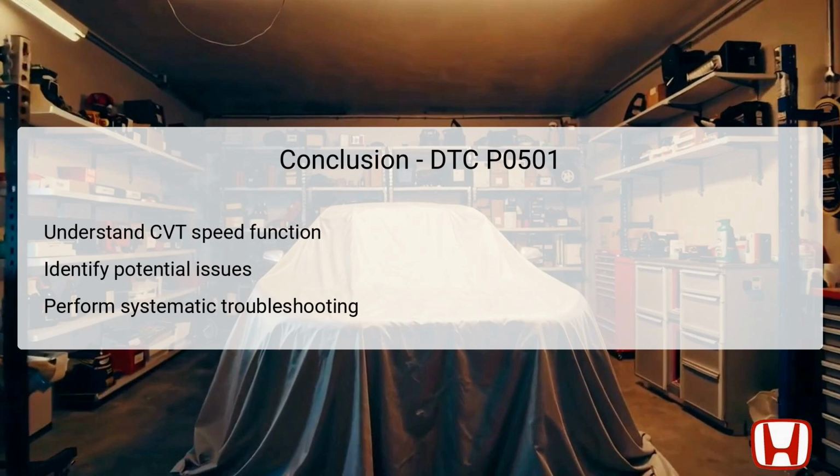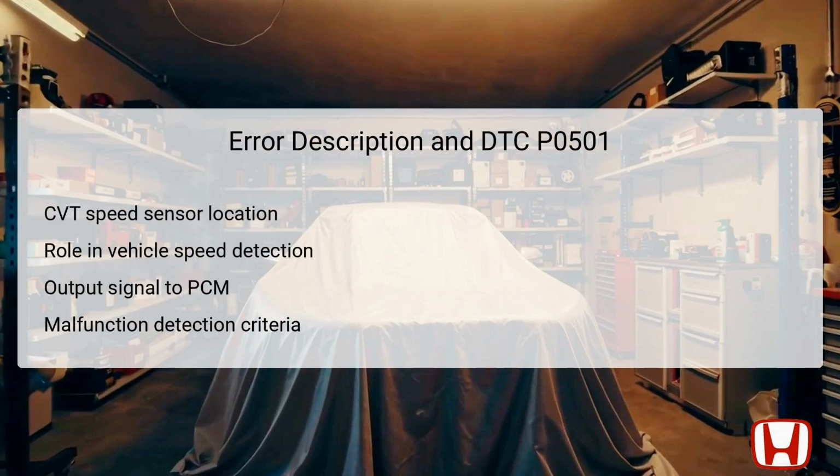Regular preventive maintenance practices can also support long-term vehicle health and performance, minimizing the risk of future malfunctions. With a methodical approach, any underlying issues can be effectively resolved, ensuring optimal driving conditions. The CVT speed sensor is crucial for relaying rotation data from the secondary driven gear to the PCM. Positioned on the torque converter housing, its primary function is to convert the mechanical rotation of the driven gear into electronic pulses. These pulses are vital as the PCM uses them to calculate and display vehicle speed.